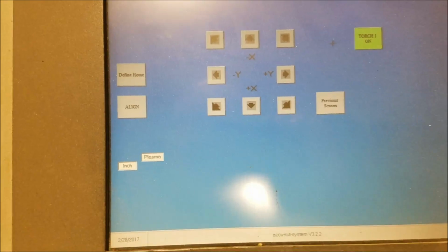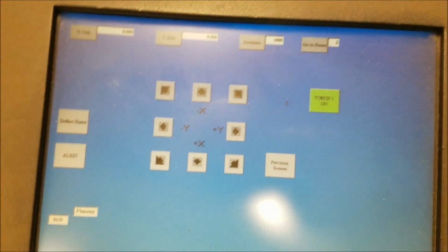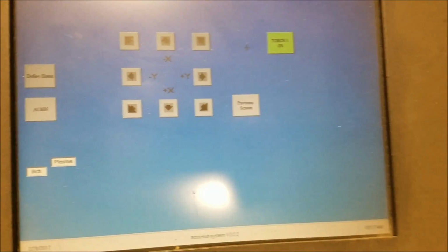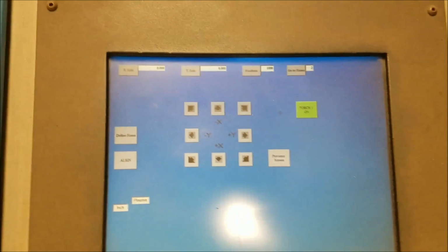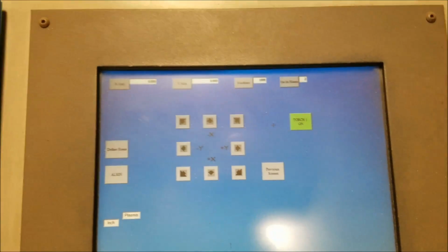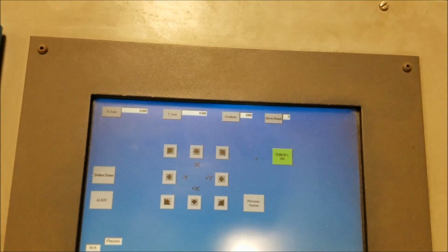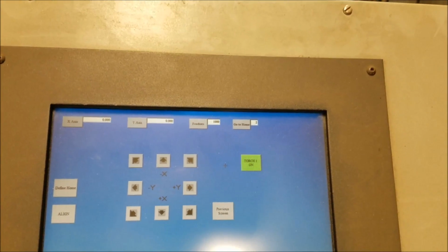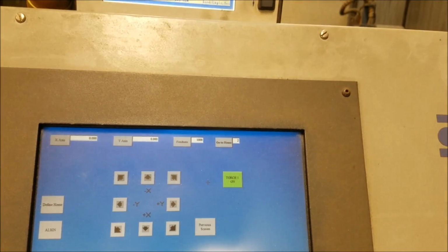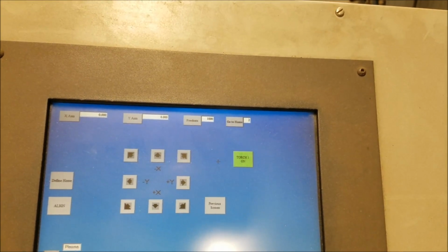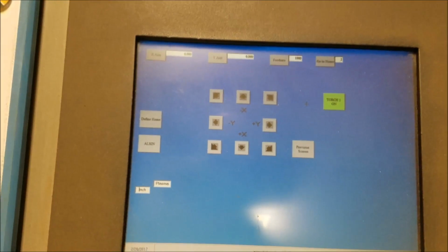So you can have, I think, up to like 10 homes. I use a home on every sheet I put on the machine. I create a home just in case I need to start over or I need to cut more parts out of that same sheet later. You can take the sheet off the machine and you can mark it if you want and save your remnants in your computer, and that's one way you can do it.